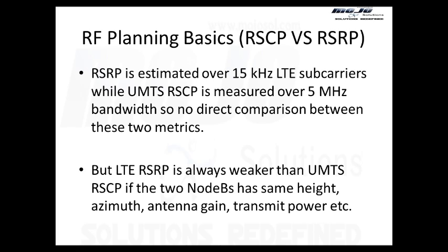Same goes for LTE FDD. If the channel is, let's say, a 10 megahertz channel and it's LTE FDD, then there will be 10 megahertz in downlink and 10 megahertz in uplink. So remember that. This is very important. Duplexing is a very important concept. It's very basic. That's why I'm covering it in such a hurry.